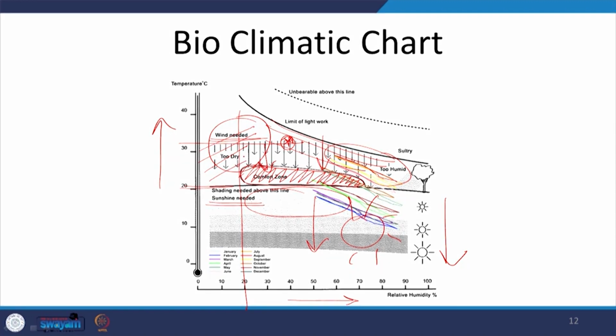Another very interesting tool tells us not just what is needed from an environmental point of view, but also how to do that through building design. We can use Mahoney's tables. Mahoney's tables are a set of reference tables used in architecture, and they help us in designing a climate responsive building.